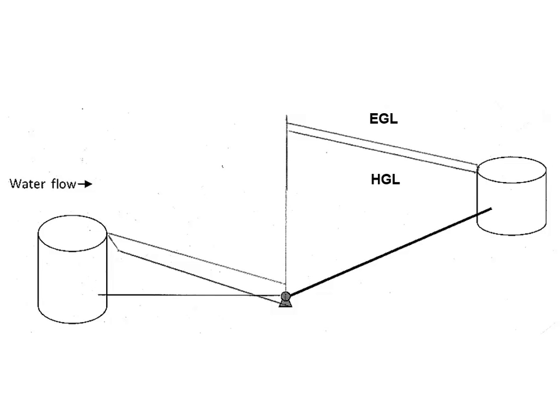Does it have to jump all the way down? You first. Does it have to jump all the way down? No, it doesn't. So there's nothing magical about the fact that I've got the EGL and the HGL down to the pump level. What I'm really looking for here is that this one is steeper than the other one. But how high it jumps, it didn't necessarily have to jump as high as it did. It only has to jump high enough that you can have some slope and still make it into the tank. If it doesn't jump high enough, then water won't flow into the tank.